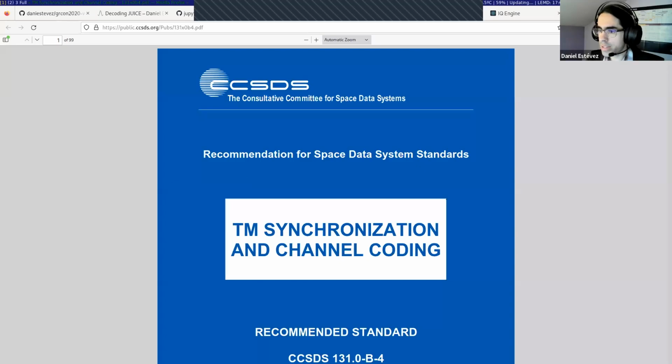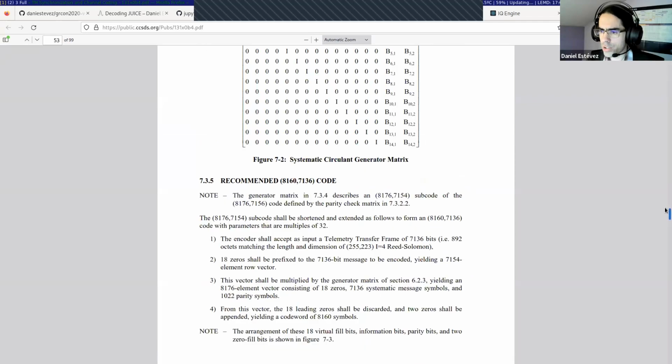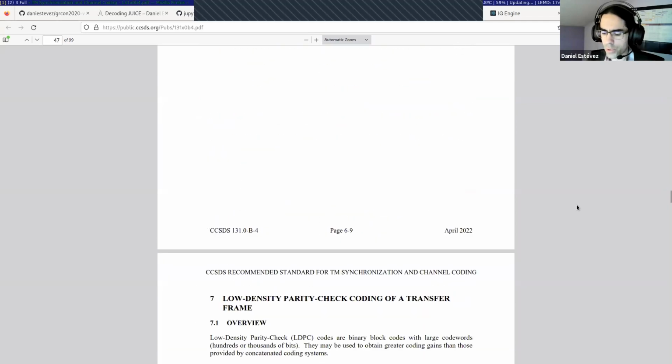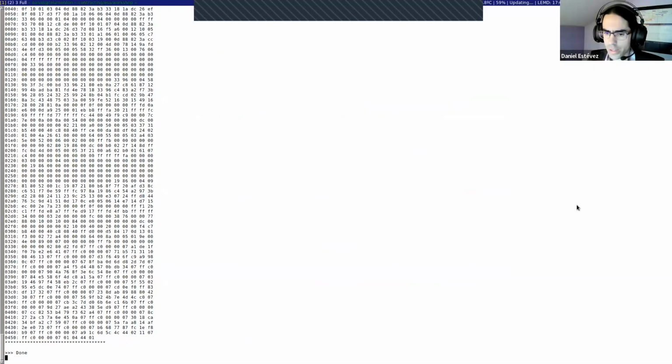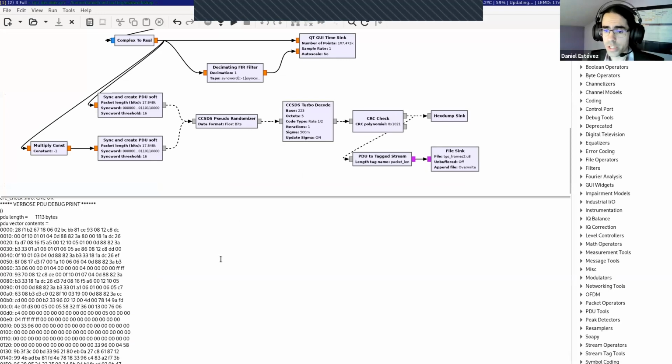And then what happens is that this is not very convenient for communications, because as you might have noticed, the frames here have fixed size. They have 1,113 or 1,115 bytes, depending on whether you strip the CRC or you don't. Here I'm removing the CRC. People in Discord have preserved the CRC. That's just a matter of convenience. Just take note that there is a CRC you can check to make sure that the turbo decoder hasn't made any errors.